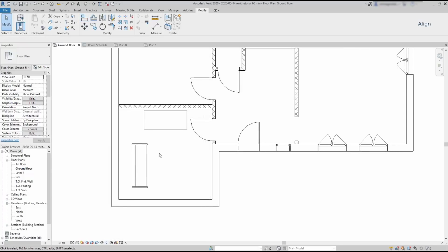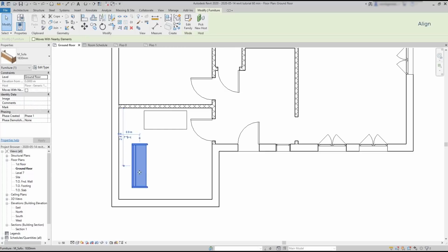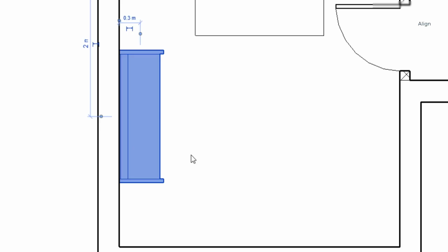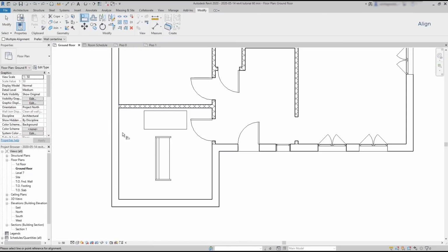Second example. Align this furniture element towards the wall. It's a nice sofa. Oh, and it's interesting to know that I can also move elements by clicking and dragging them and placing them where I want. If I try to put the sofa against the wall, I can't do it with 100% precision. Although with the Align tool, I do the same process as before, and this selection line is not the one I want, because the sofa would go inside the wall to match the center line.